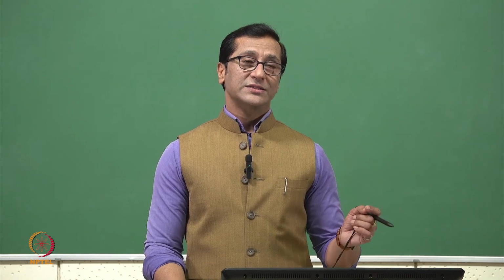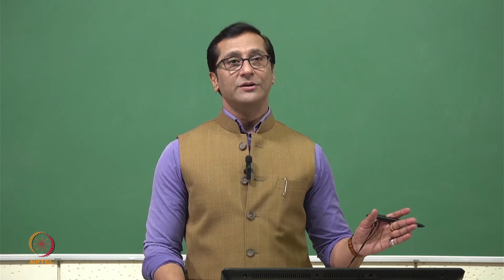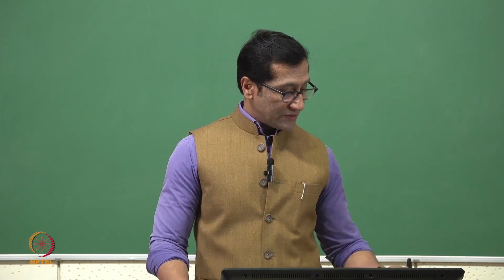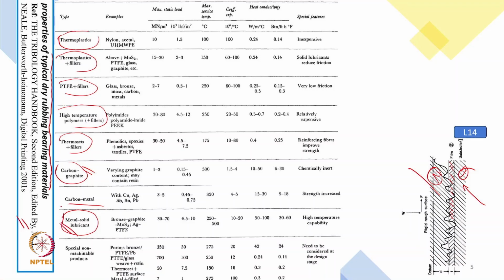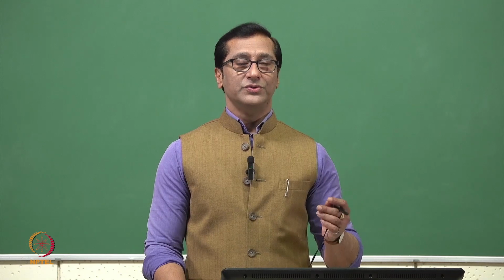When micro cracks get developed, and then if some sort of hot spot comes, it really heals that crack. So there are self-healing properties in soft metals that will also be covered. You can see here they have provided the maximum static load, and in the previous lecture we covered 10 megapascal as one of the constants in a bearing design. Now for thermoplastic it comes down, instead of 10 it's 2 to 7 when we are using PTFE. Many times people immediately say, oh, we use PTFE, but we should know that it has much lesser properties compared to other materials.